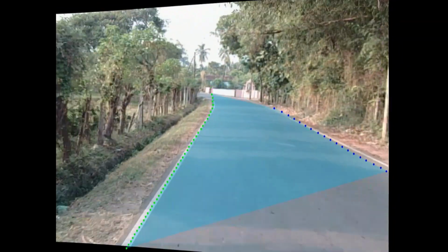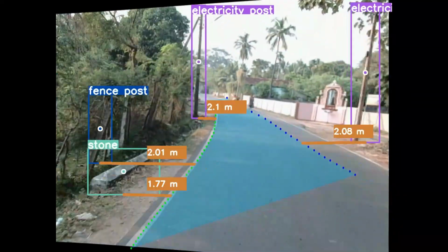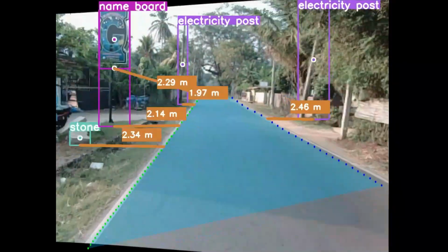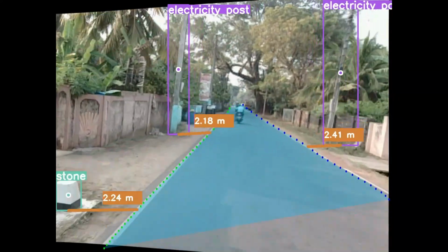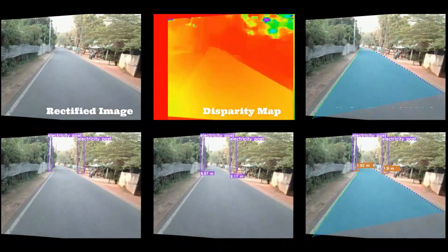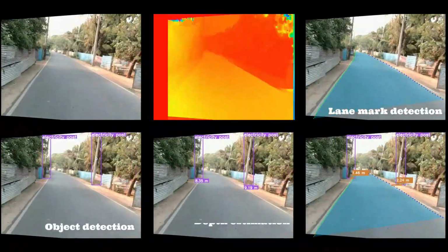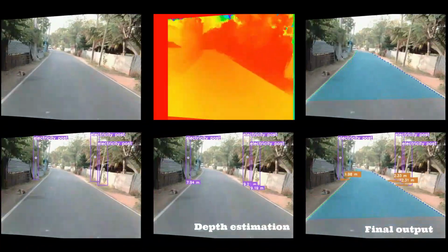Let's see the final output from the system. Here you can see, off-road obstacles are being detected and the distance from the lane marking also calculated. In this combined video, you can see all the steps involved in this process from rectification, disparity map calculation, lane detection, object detection, depth estimation, and the final distance measurement.